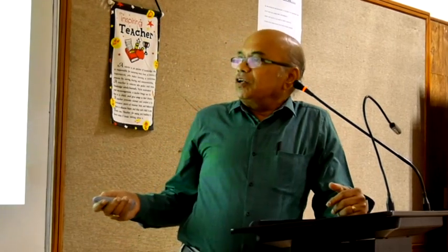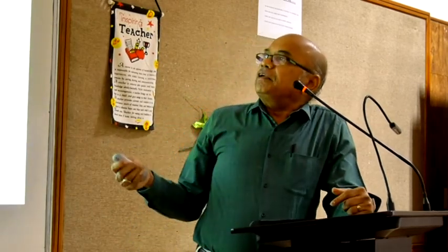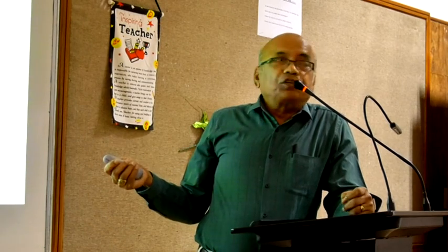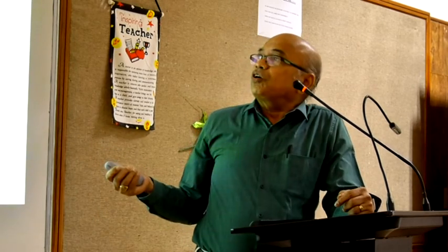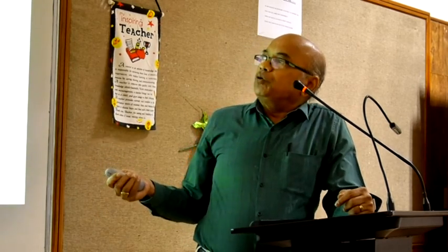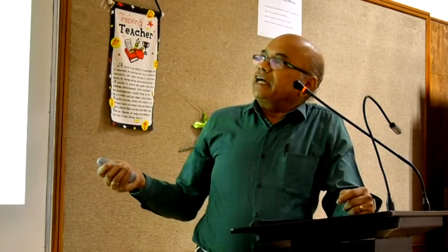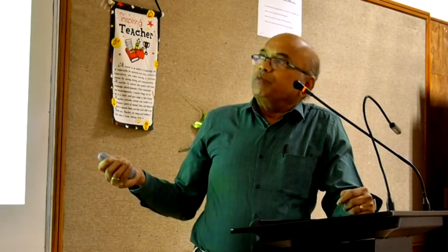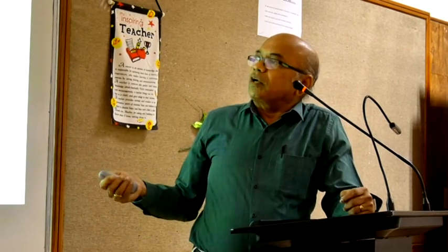Because there is no mutual coupling. ZQI equal to ZPI, because the other elements are equal to 0. And ZQQ equal to ZPQ plus YPQ, and that is for the diagonal element. So for the diagonal element only, no mutual coupling. Therefore you get this one.